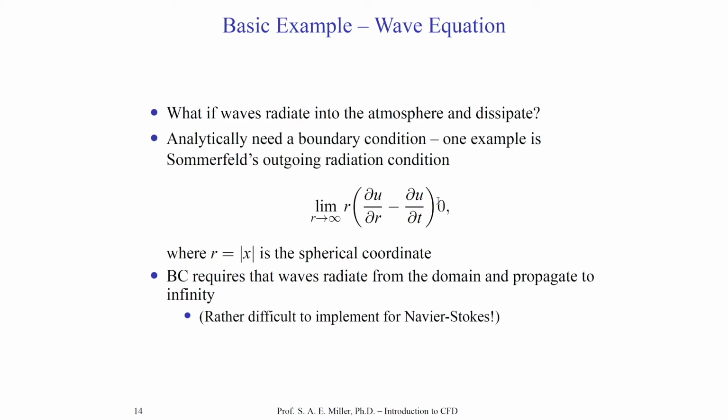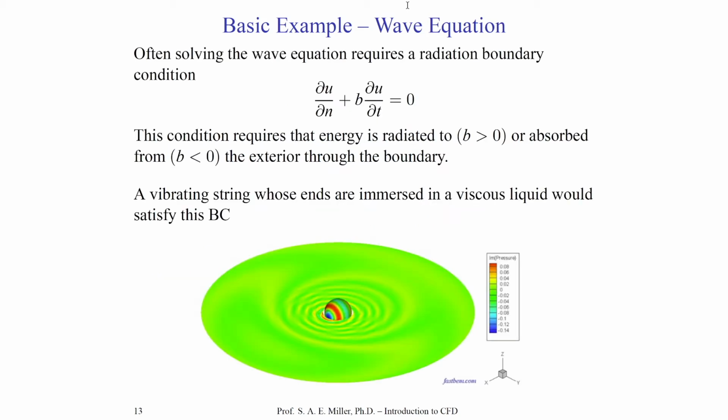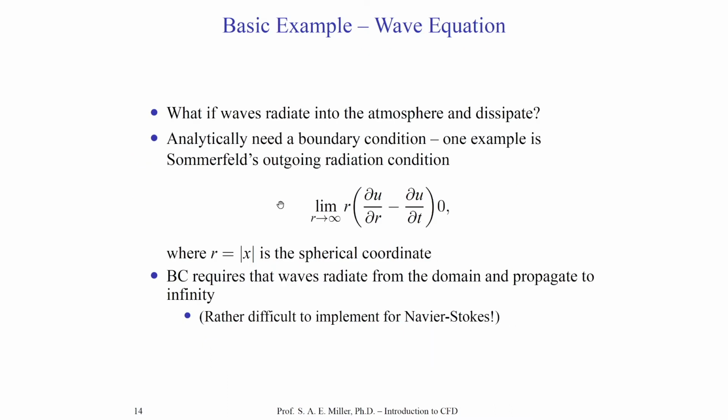You can see we're imposing a type of solution, a reduction of the governing equation, of the wave equation, at the boundary far away from the source for large r. This is a typical radiation condition. In fluid dynamics, there's something very much like a wave equation, but applied to the full equations of motion, called the far-field boundary condition. We will be applying that in this class, and it even lets us impose some basic underlying mean flow, for example, a Mach number of 0.2.